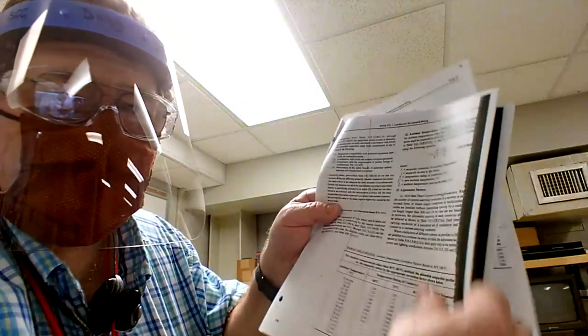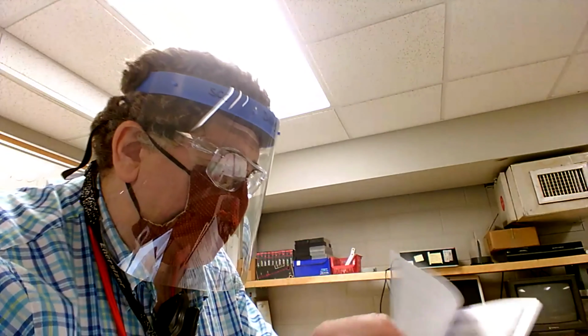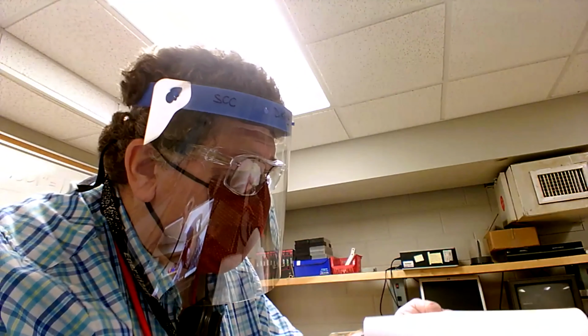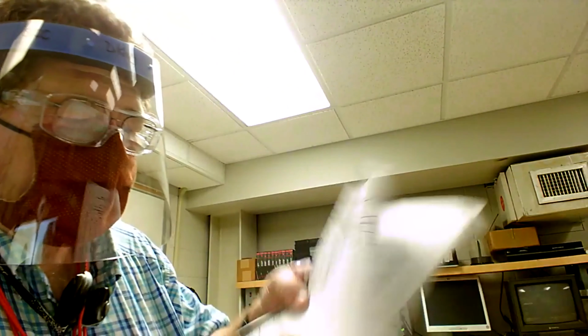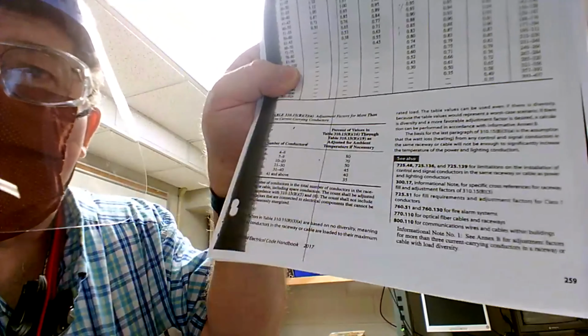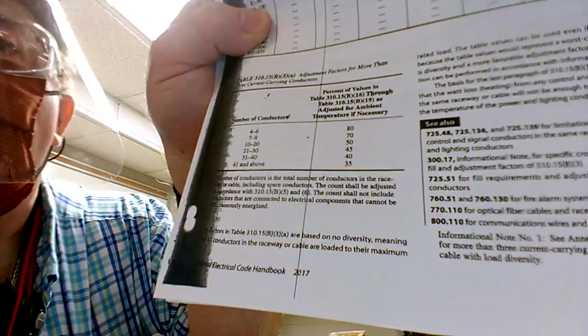So this electric code material shows those charts for doing the adjustments based on temperature and all that. It's in that one PDF that you can download to your phone or your computer. This is the table that shows the adjustment factors for how many wires you have in a conduit. All that's in that same PDF document with the wire chart. So you need that one as a definite.